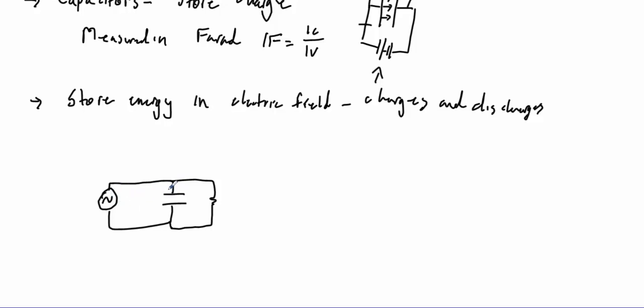So there's not enough time for the charge to build up and create that voltage back the other direction. At a very high frequency, this acts like just a straight conductor, and the current goes right through here and around this loop. However, at a low frequency, the capacitor is going to charge up. That creates a voltage opposite of the source voltage, which basically says, instead of the current coming through this branch, go through this branch. And so what we get is what's called a high-pass filter.